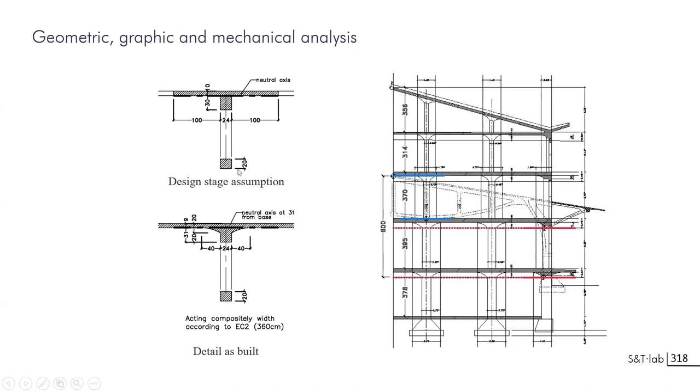And you will have another line here, just a minimum of 20 centimeters to be able to have the tension reinforcement passing through it. At the end, you will have a kind of rounding, as Maya does very frequently on each of the bridges, using a parabolic line, so you know how to draw a parabolic line, and to have a stiffening member.